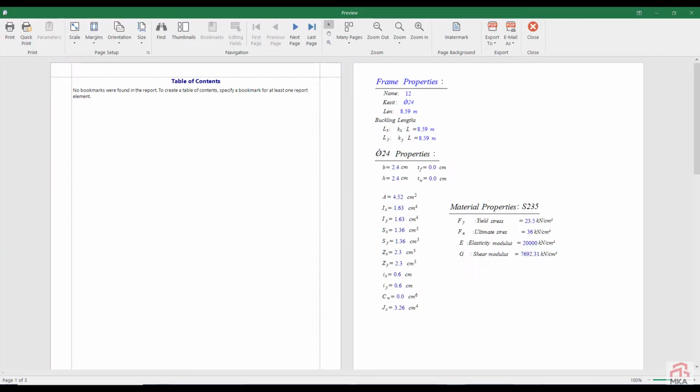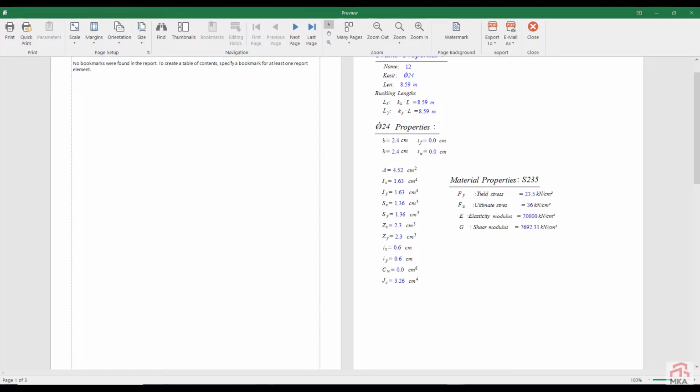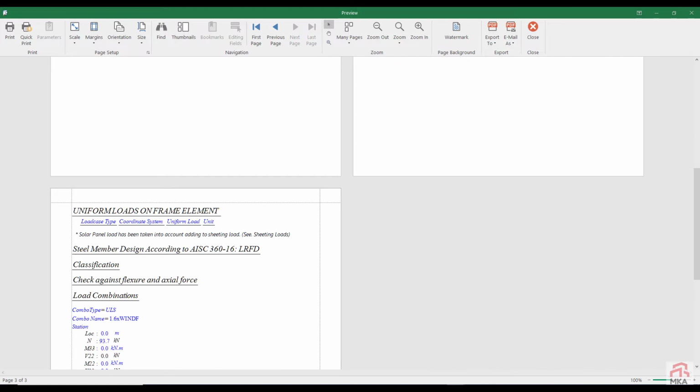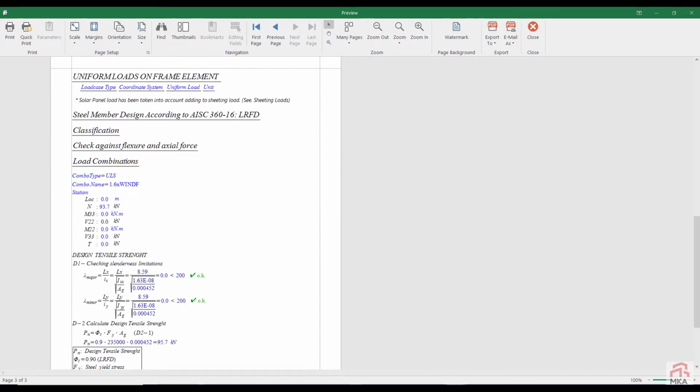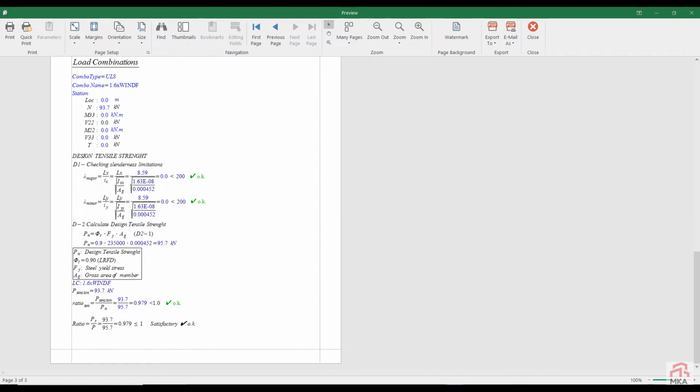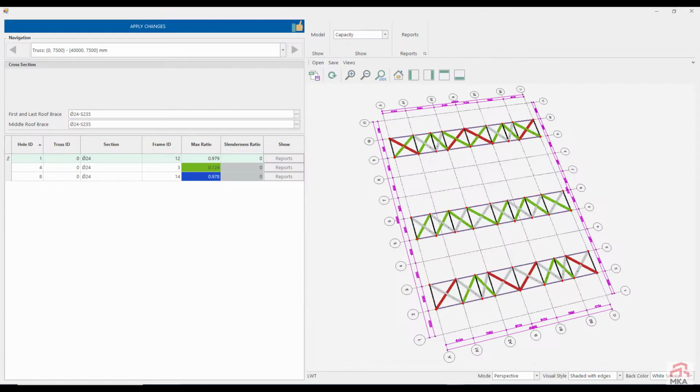From this page we can access the detailed report of the calculations. Here is the calculation of the 24 rods. We calculate according to AISC 360-16. They are only tension members. Although at the limits, the sections are sufficient for now.